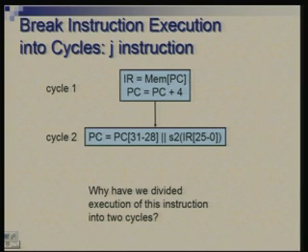The reason for that is we want to do these operations sequentially. The 4 bits we need to pick up from PC part is actually after PC has been incremented. So, after PC is incremented, one cycle is over. Okay. In the first cycle we are incrementing PC and the result is put back in PC. So, those 4 bits are picked up in the next cycle and put together with instruction. Also you would notice that it takes one cycle to fetch the instruction. So, although what is being done here is not a time consuming activity, but since it has to be sequenced after that, it is occupying additional cycle.